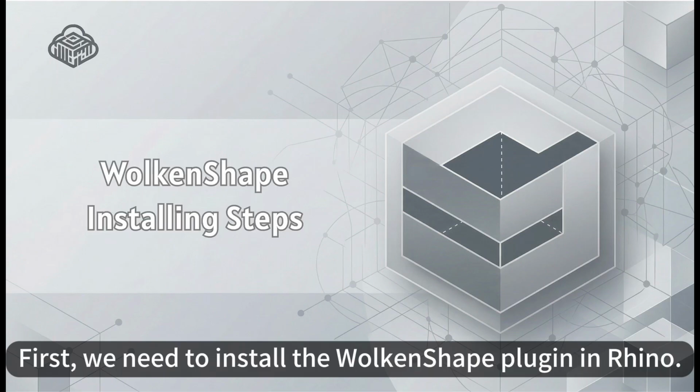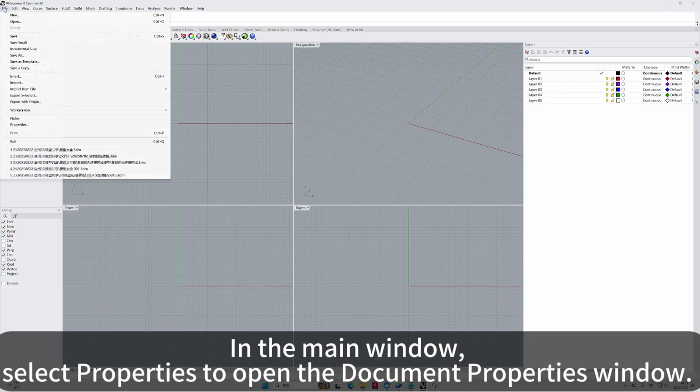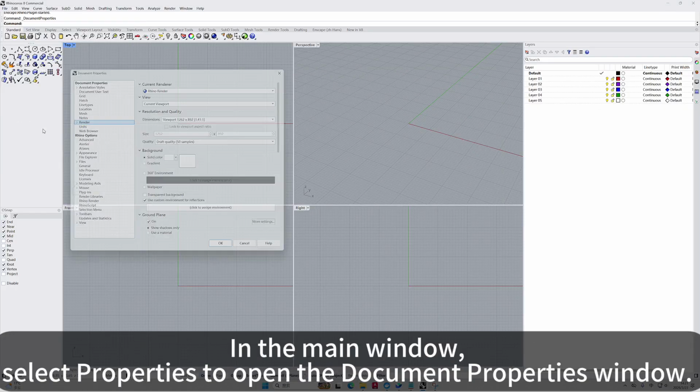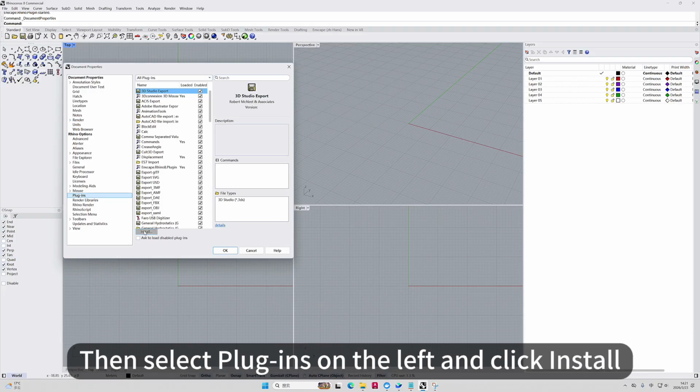First, we need to install the WolkenShape plugin in Rhino. After downloading and extracting the WolkenShape installation package, open Rhino 8. In the main window, select Properties to open the Document Properties window. Then select Plugins on the left and click Install.